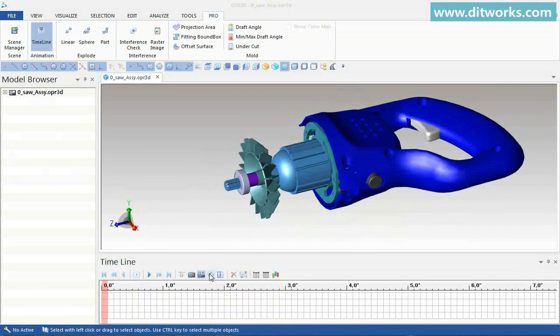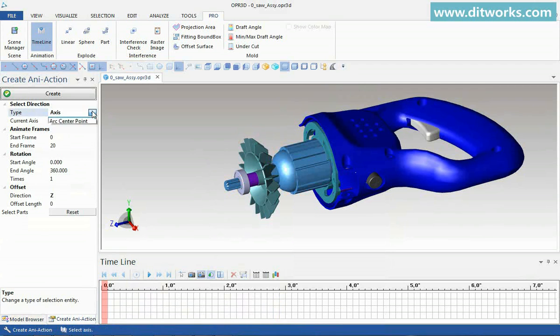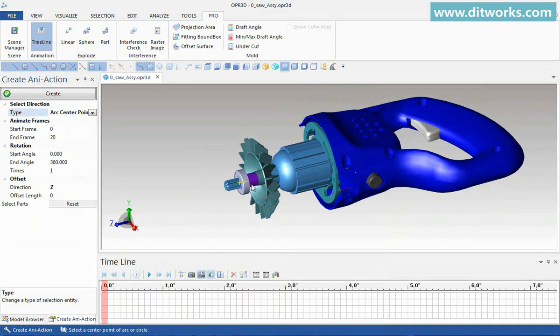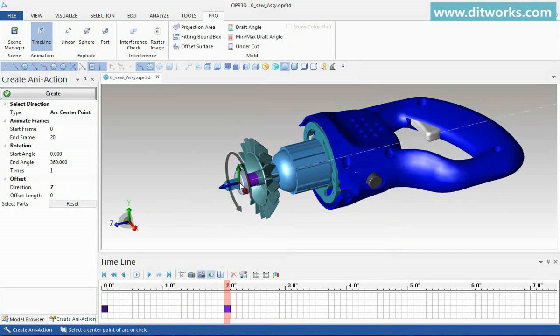You can rotate the desired model by selecting it, move it by giving an offset value, and rotate it. After you set the rotation direction and interval, number of rotations and the offset distance, generate, and you can see the selected model is rotated with offset rotation.